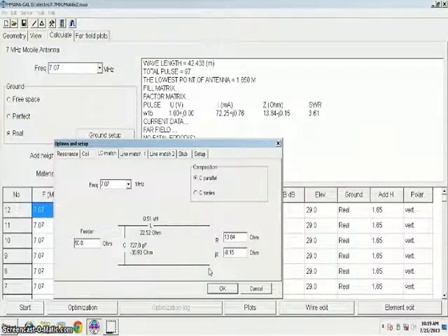The ground plane only replacement for car roof, so you don't need real ground plane at the practice. So this part goes to the ground because car roof is painted, so you should connect this to the unpainted part of your car roof.